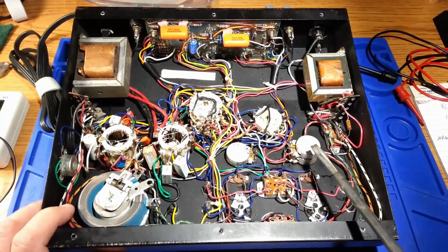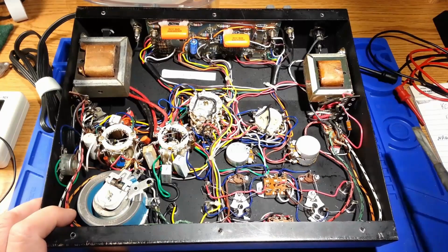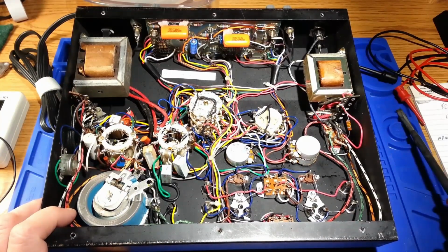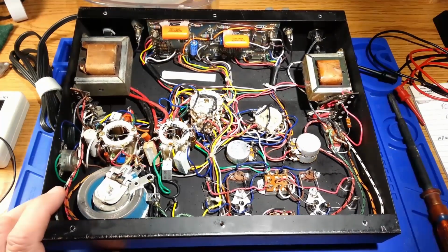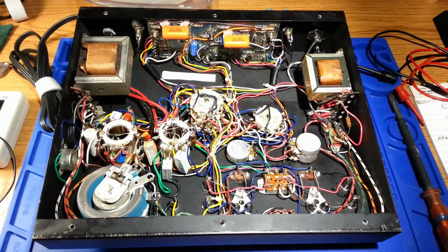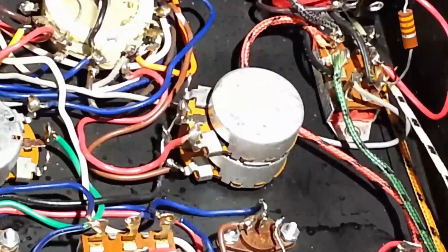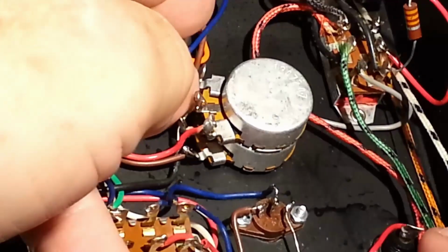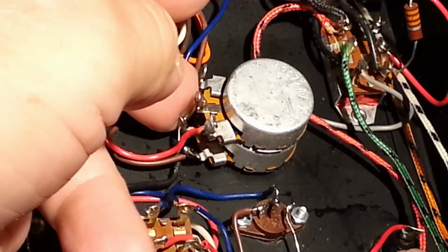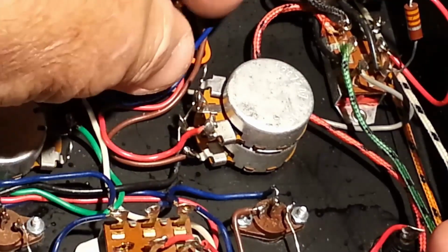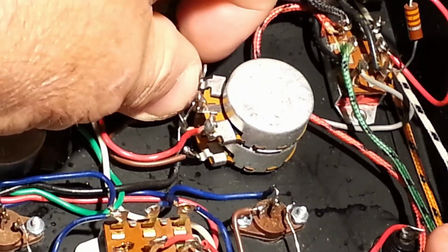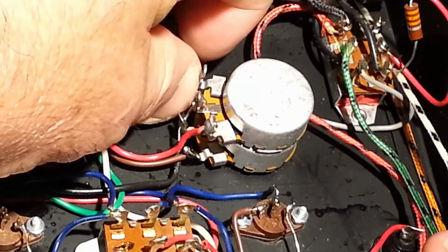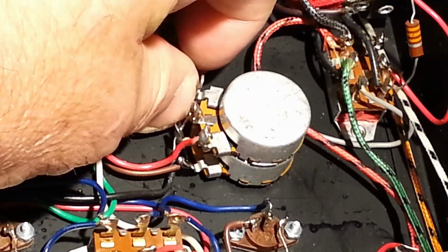I have the adjusting potentiometers for the power transistor gain, and I double checked the wiring on them. One design part to them is they don't have a connection on the double pole potentiometers. They don't have a connection on this one pole here, and the way it's behaving, the potentiometer is almost behaving like it's backwards.